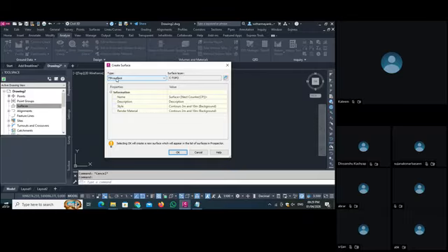It is not mandatory to go for the TIN volume surface to create a volume, because what happens sometimes, we get a small piece of work, like they provide 2 sheets and tell you that we want to calculate the volume of the surface, do it in half an hour. So for that, they use the TIN volume surface, so the work is easy. But it is not mandatory. If you make the TIN surface, then again you can calculate the volume, but in a slightly different way.